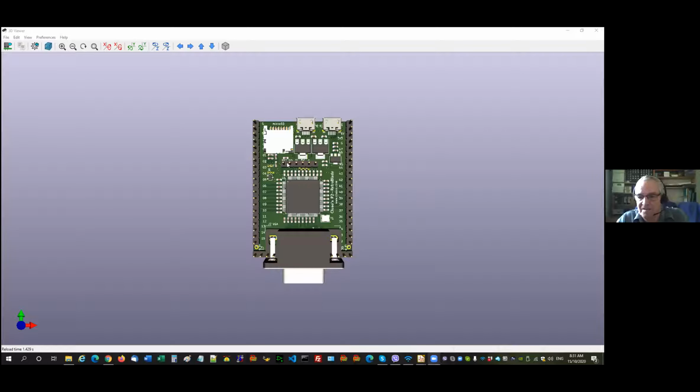The catch is with the prop tool, we need the prop plug has the transistor reset circuit. You'll notice all my boards for years now have an optional reset circuit. So if we go back to this header, so back to share screen. This header here is the 6-pin header for that cheapy USB to serial port.